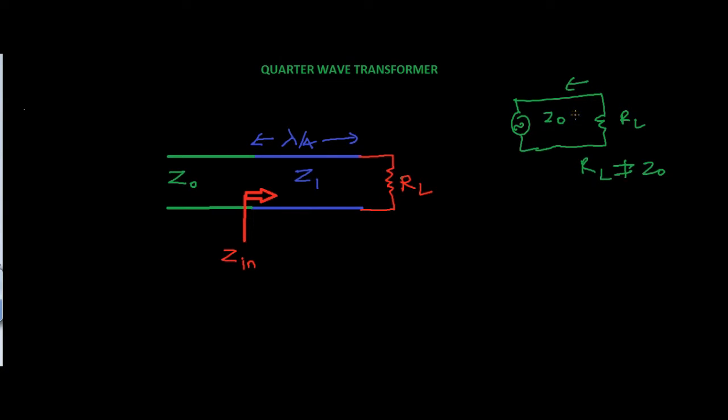That is, full power will not be delivered to the load impedance RL. So in order to deliver full power to the load, we need to make sure that the load impedance is matched. This is an important criterion not only in transmission lines, but in several other things as well. Matching impedance is very important to deliver full power to the load.